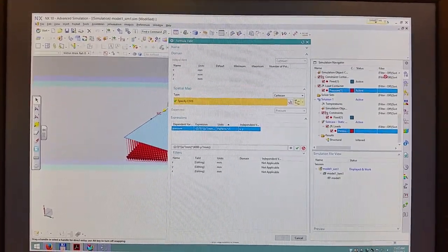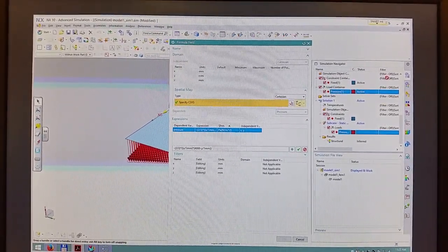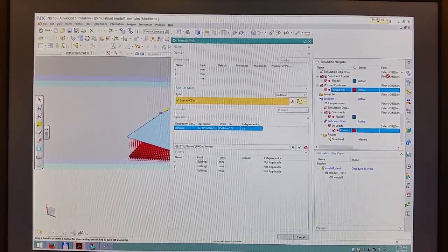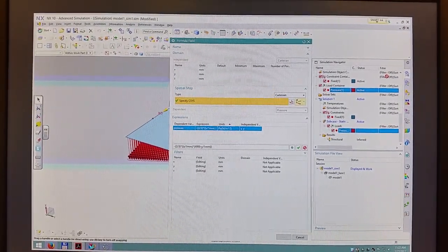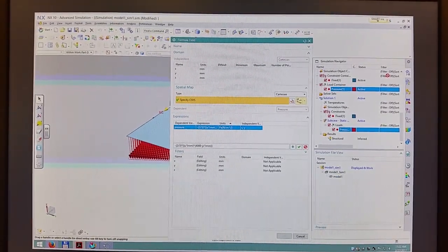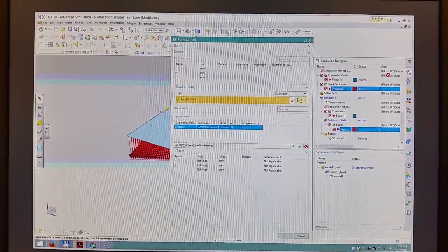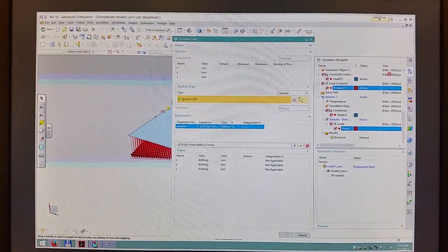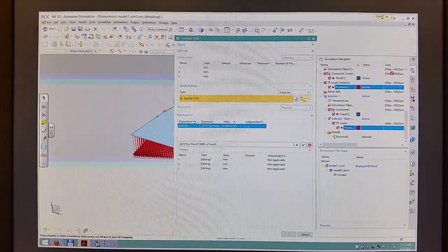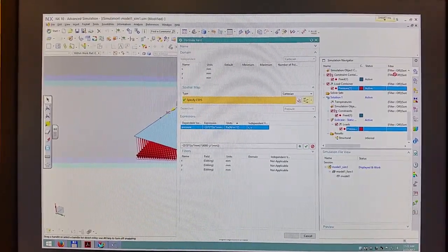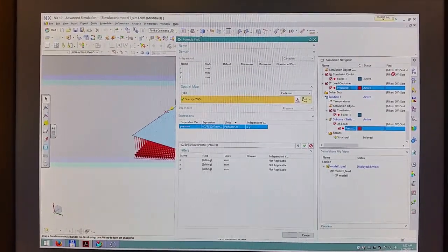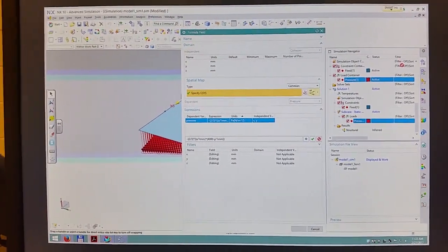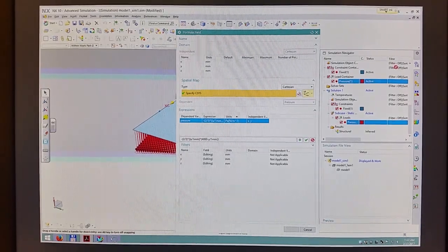So I need to divide by what? A million. Okay? I need to divide by 1 times 10 to the 6th. Because this equation on the board, it's meters. I have meters times meters. When I wrote the equation in NX, I have to define it in millimeters. So I have 1,000 millimeters times 1,000 millimeters. Okay? So I bumped up the amplitude.